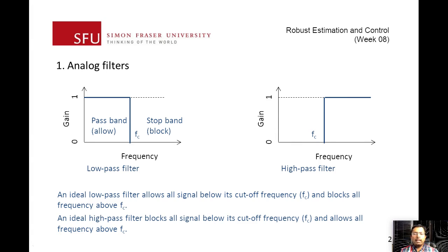A typical example where you would use this is if you have a gyroscope in your device. It's going to have a small drift, and what you can potentially do is use a high pass filter to cut off some of the DC bias or the drift in your signal, and allow only the high frequency component to pass through.